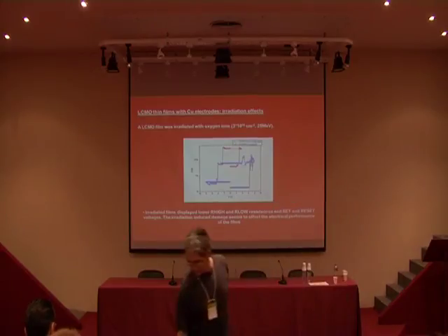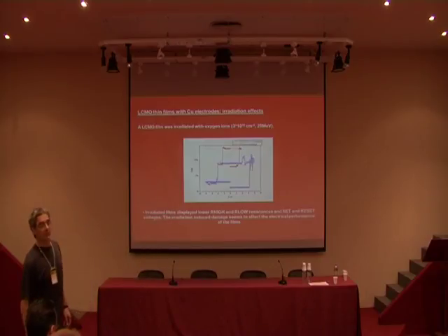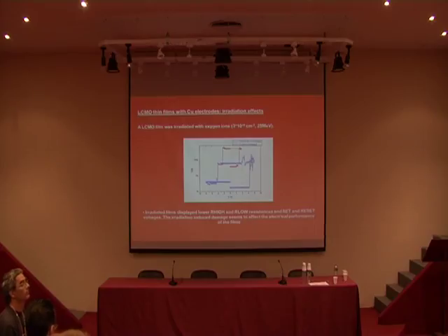Diego, I have a doubt. When you apply the high compliance and you complete the filament, how do you get back to the high resistance state? I do not understand. It can be any of the mechanisms known for filamentary regimes. You can burn it by Joule effect, for example. But in this way, you are not guaranteed that you are going to have bipolar. It could be unipolar. It can, indeed. But for bipolar, you need some, I mean...